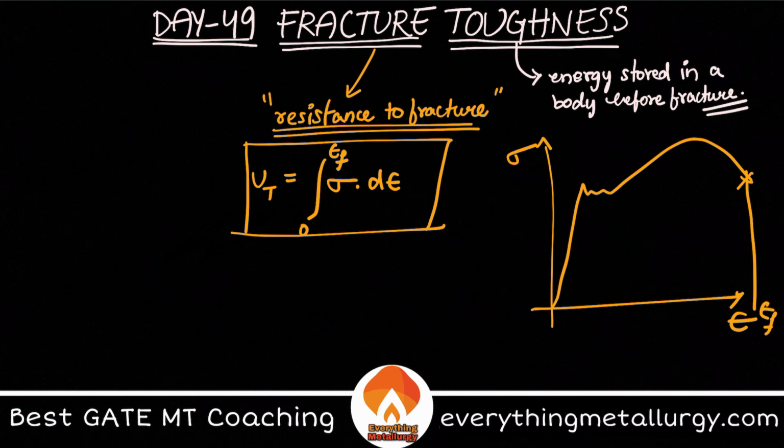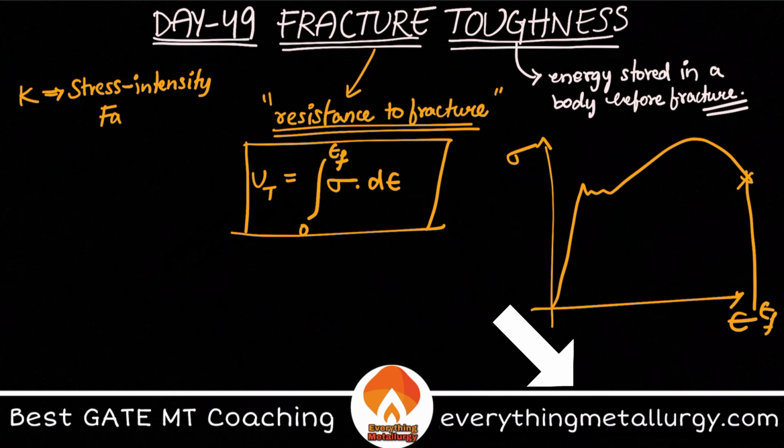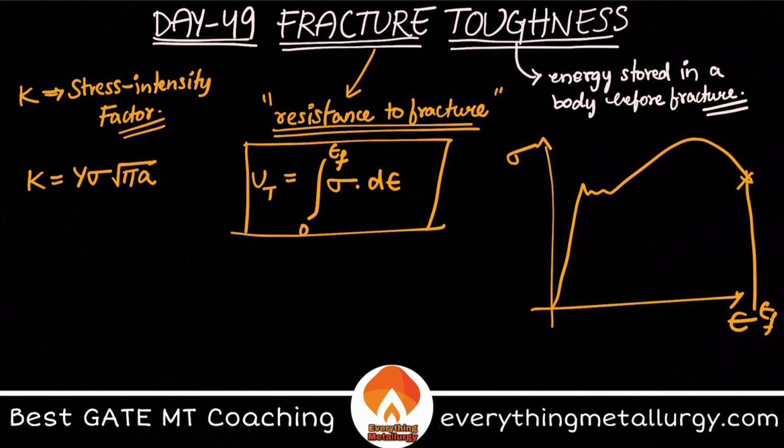So this is one kind of approach from mechanical testing. This particular principle uses mechanical testing phenomena, finding stress strain curves and all the stuff. But there is one more approach, via fracture mechanics. There we have something called K, which is the stress intensity factor, written as K equals Y sigma root pi a.